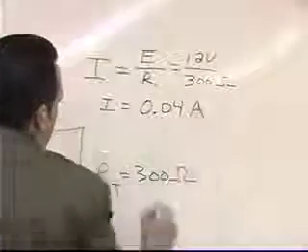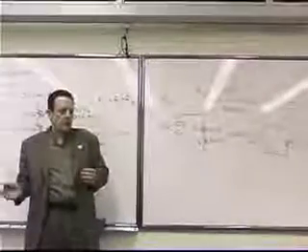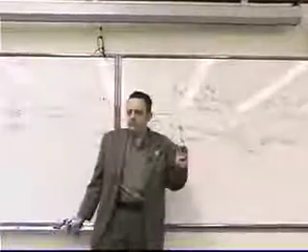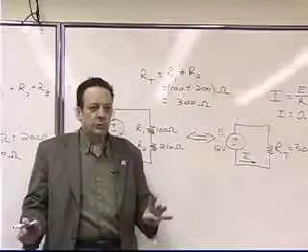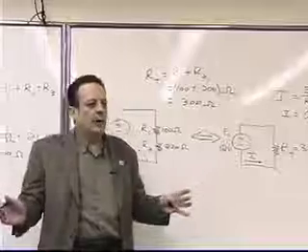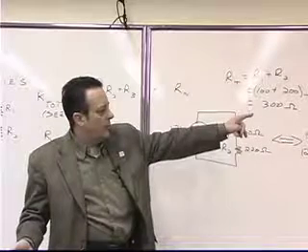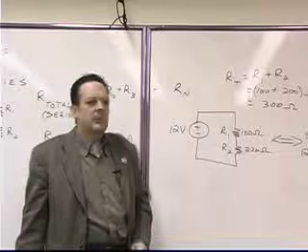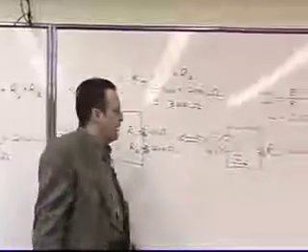So this is equal to 0.04 amps. Now, because of the fact that you need to know how to make conversions in the metric system, okay, if, let's say, you were given an exam, an aptitude exam for a company, and they gave you this exact problem, but it was a multiple choice problem, and the only choices that you had were in milliamps, then what you would have to do is convert that number of amps, 0.04, into milliamps. And how would you do that? Right, you would multiply it by 1,000.